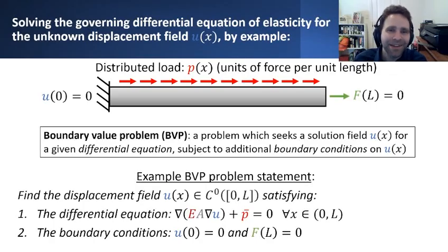At the right boundary, we choose to impose zero force there. But it doesn't necessarily mean that there isn't a boundary condition there. In fact, we are imposing a boundary condition. It is, however, a force boundary condition, kind of the one-dimensional analog of a traction boundary condition, imposing some constraint on what the applied load is on that right-hand end, just saying that it's equal to zero.